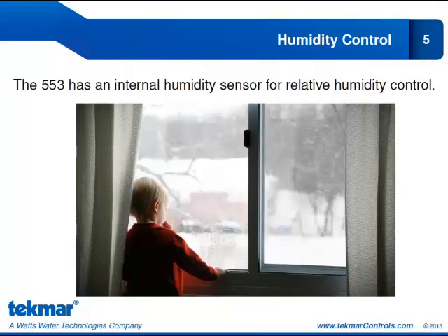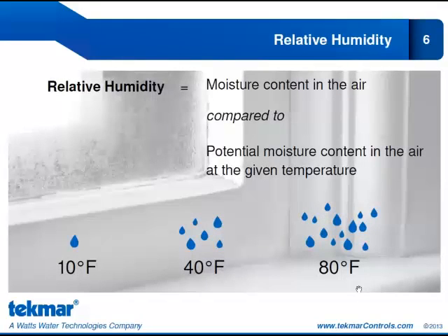Over the next few slides, we're going to take a look at the humidity control function of the 553. Let's review the concept of relative humidity. It is the moisture content in the air compared to the potential moisture content in the air at the given temperature. So relative humidity changes with the air temperature.